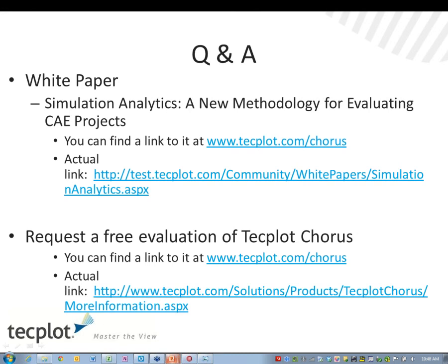Okay. There's another question about surrogate models. It seems to be an area people continually ask questions about. We do have just two models. Is it worth talking about, kind of long-term where we're going with surrogate models in general? Well, there's a couple of things we want to do. The two we have now are the second-order response surface, which is really a functional fit, a least square fit of a quadratic equation to the data, the metadata, and kriging, n-dimensional kriging.